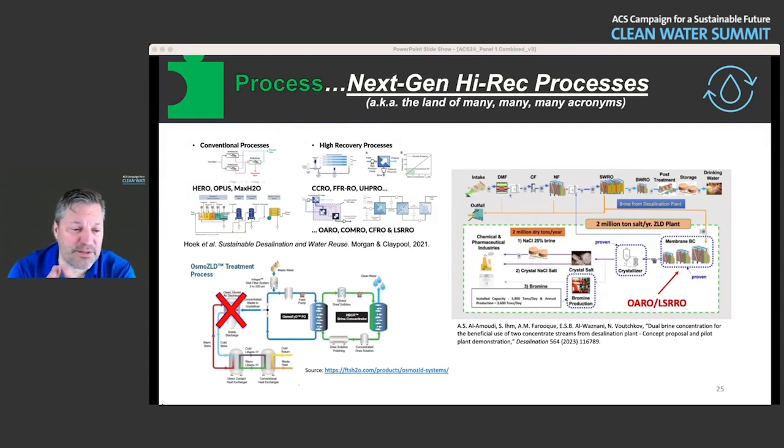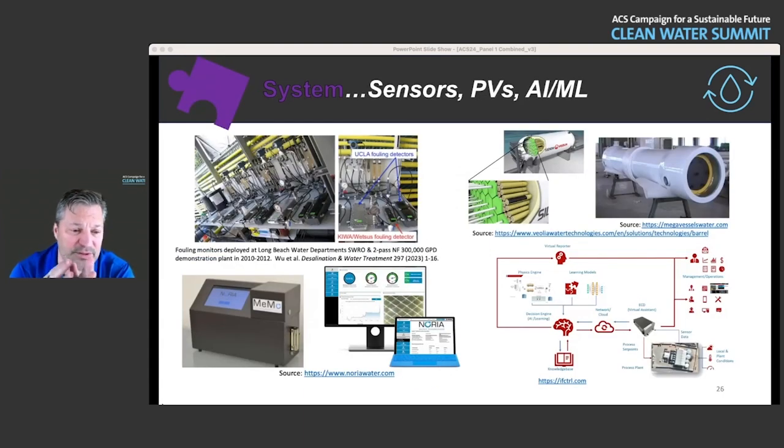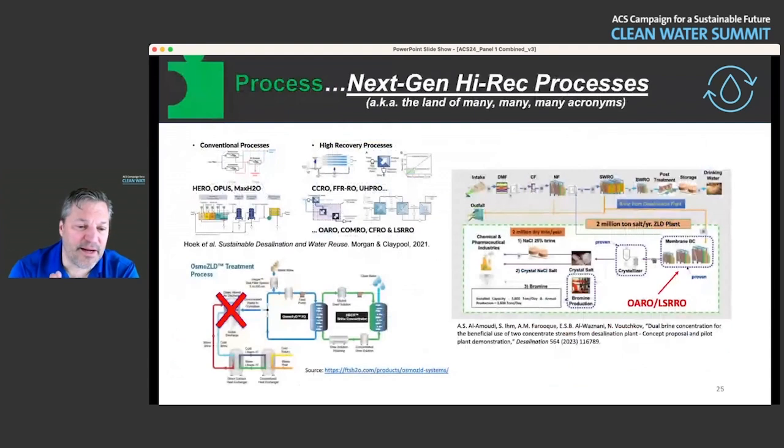And below, we're seeing the emergence of non-thermal membrane-based crystallizer technologies, which can involve a combination of forward osmosis and reverse osmosis membranes. And so we're getting into the range of the ability to both concentrate and crystallize brines into a dry salt or into a salt without adding any thermal energy. So purely membrane-based and purely electrified processes.